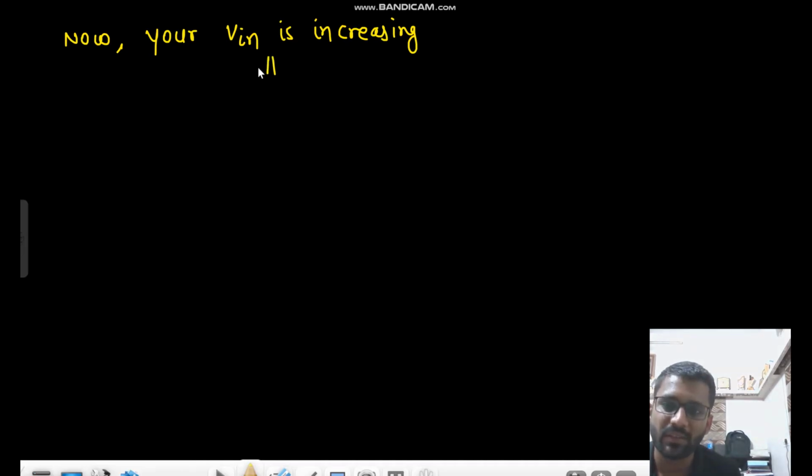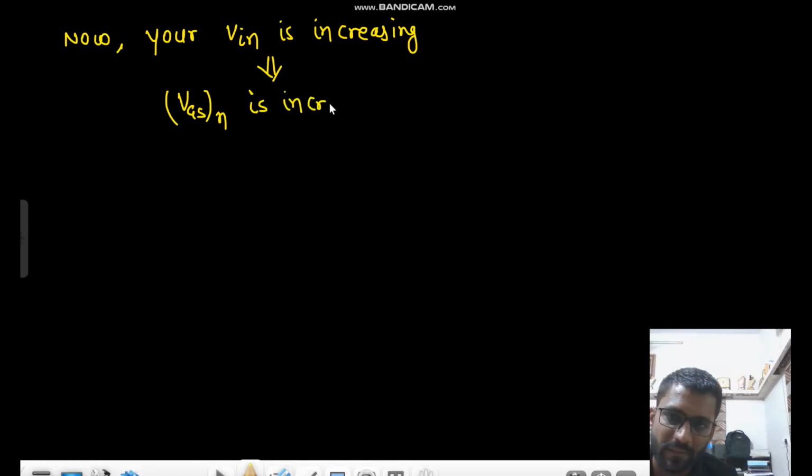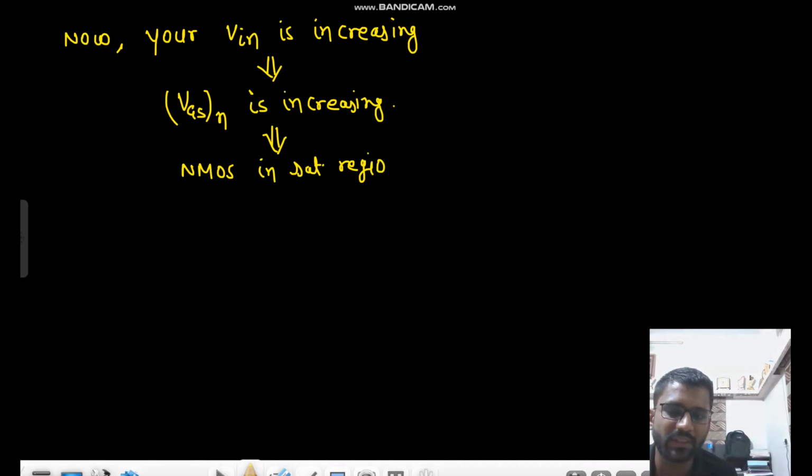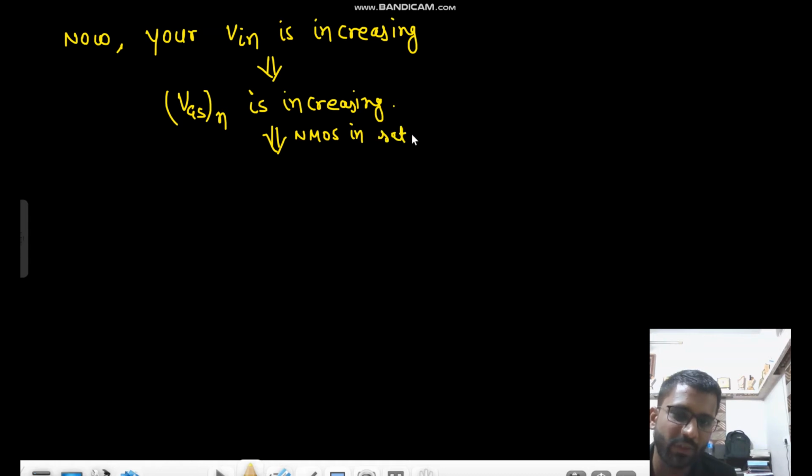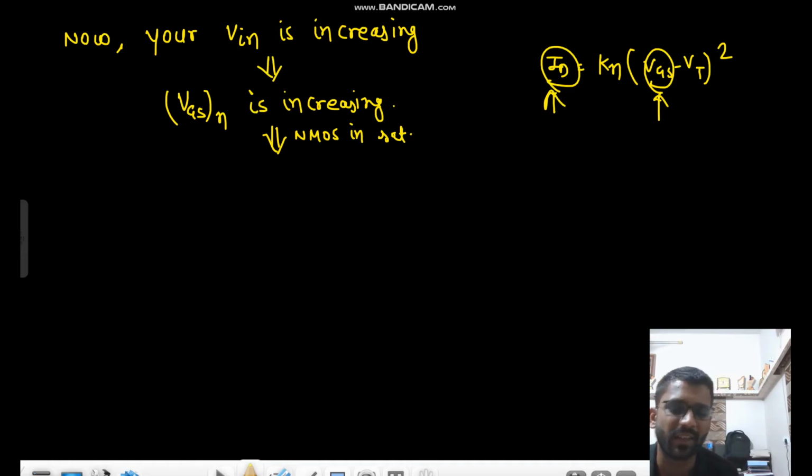That means VGS N is increasing. Here I should write NMOS in saturation. In saturation, if your VGS is increasing, what is the current in saturation region? ID equals to some Kn dash times VGS minus VT whole square. If this value is increasing, that means your current is increasing, right?